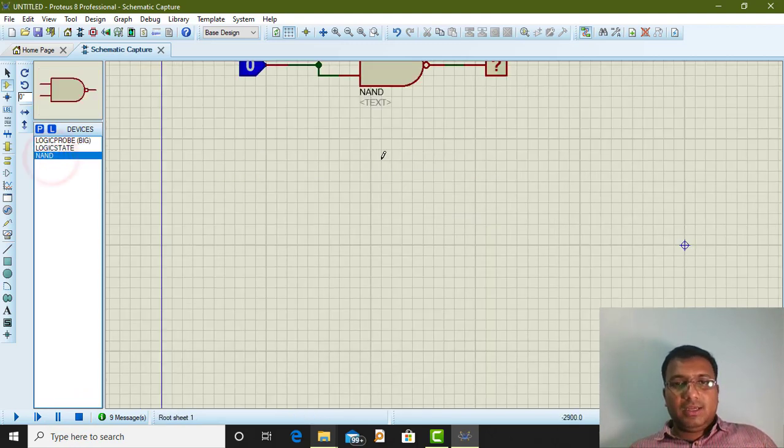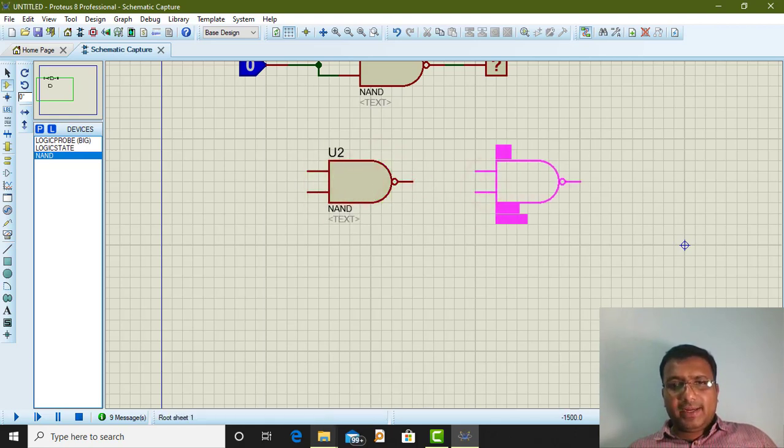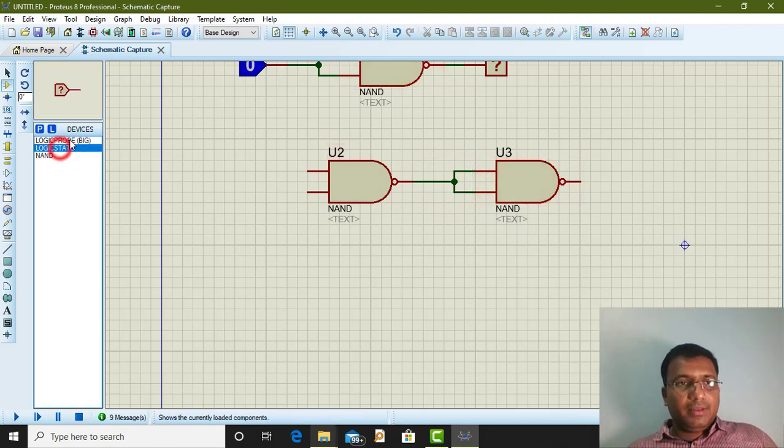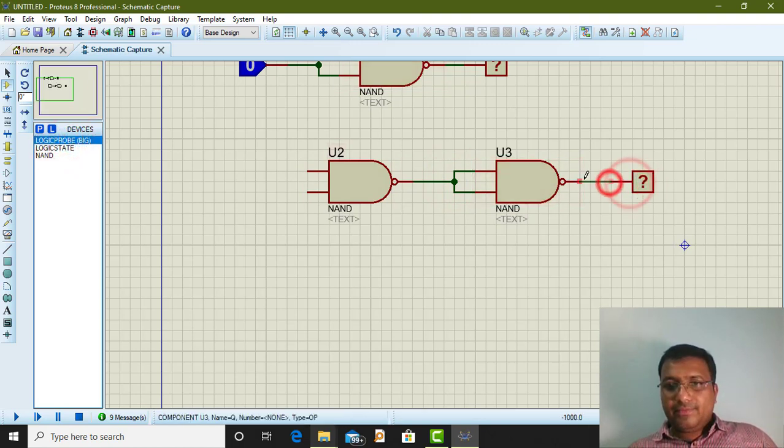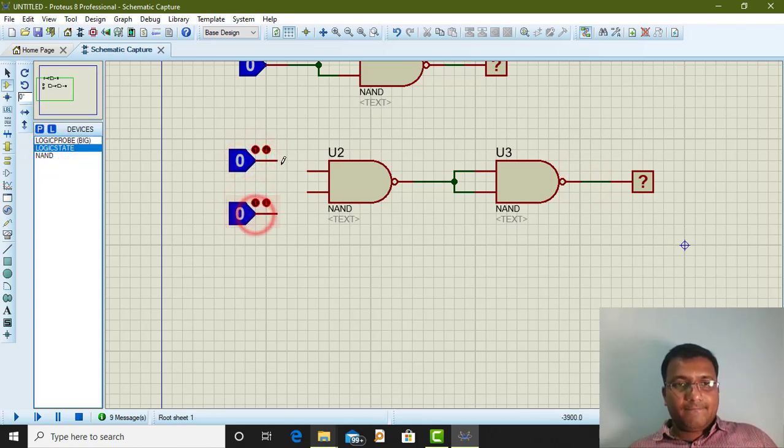Okay, for that again I will check NAND as an AND. I will take one input. It requires two NAND gates, so I will make this input as a short, give here. So I will use this inverter circuit here, and then logic state will connect it here like this. Now states I am going to connect it like this. There are two inputs, input A I am giving here, input B I am giving here. Alright, so A and B are the inputs for the first NAND gate. Then secondly I am using inverter. Okay, two NAND gates, I can do NAND as an AND.